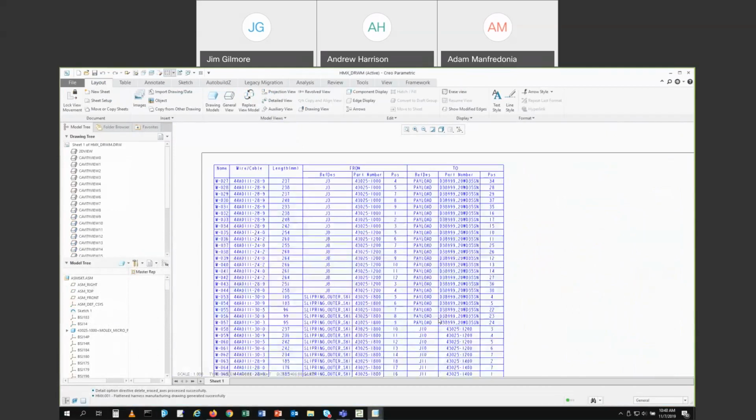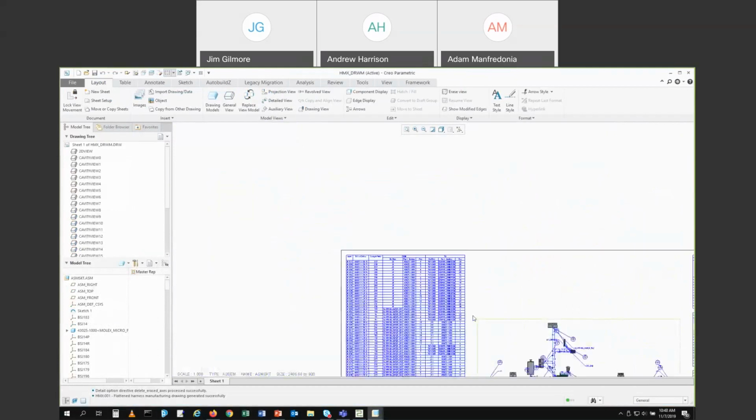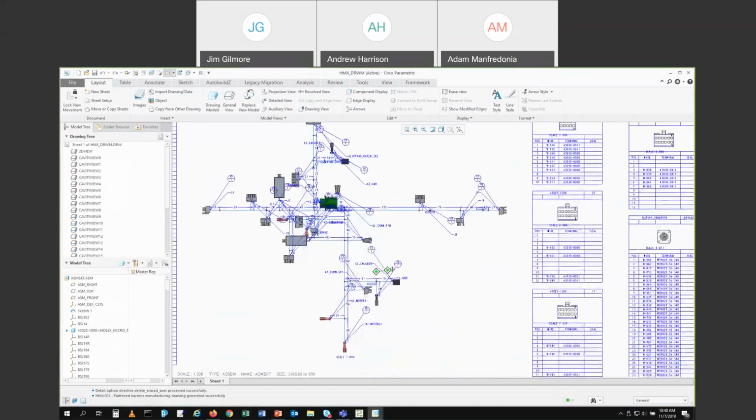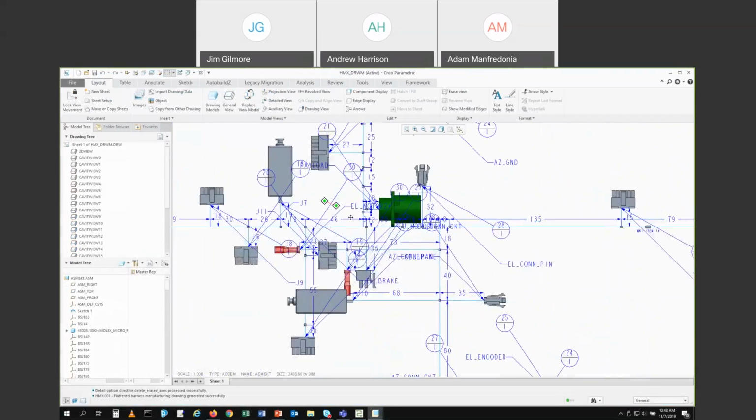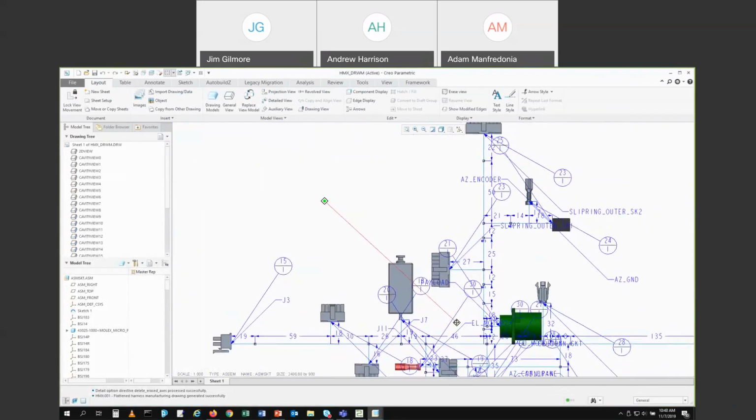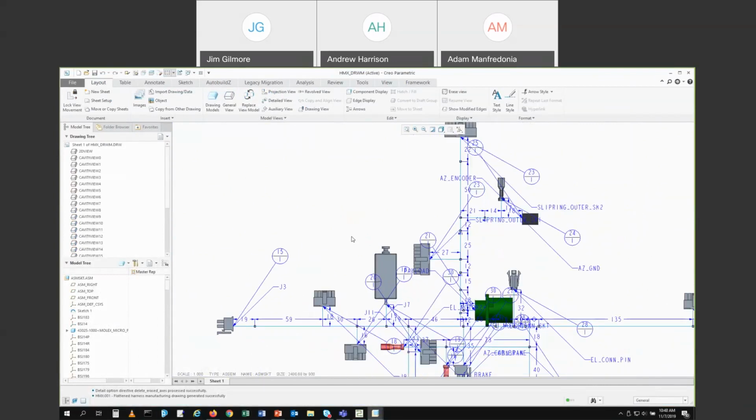Again, same number of wires, spools, lengths, so your cut list information. It's a little more complex as far as what we're looking at within the context of our view and our diagram. The things that you're going to pretty much have to clean up inside here are a lot of these labels. As these get more complex, the default position of the labels isn't always where I want it to be. So those are going to have to be moved around.